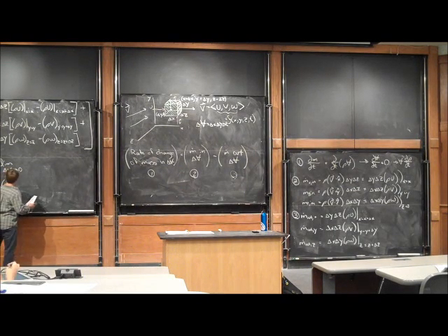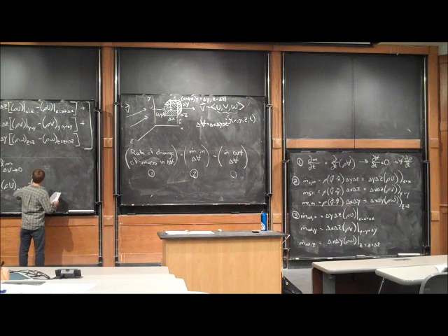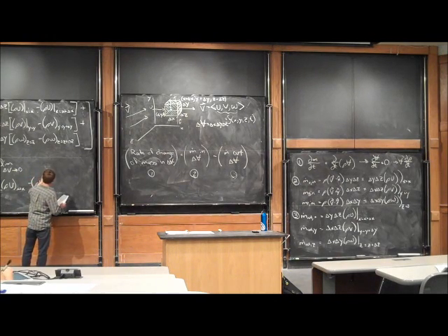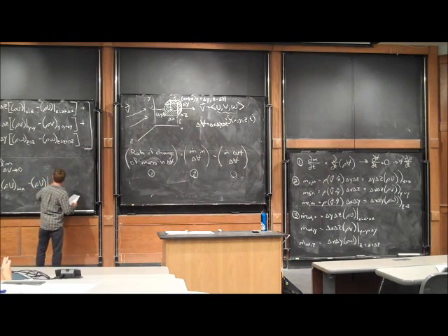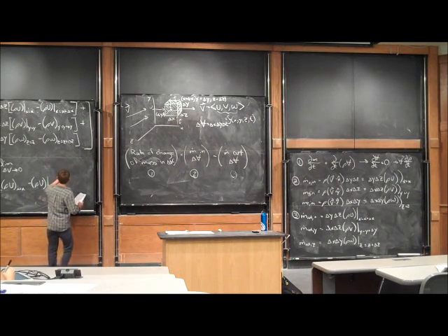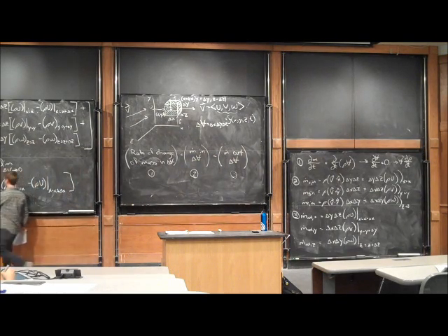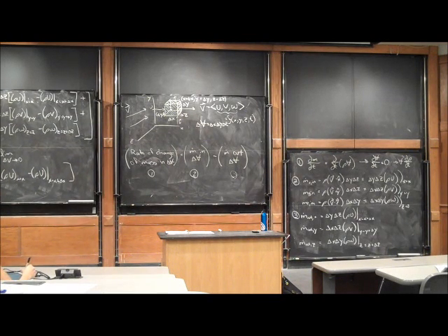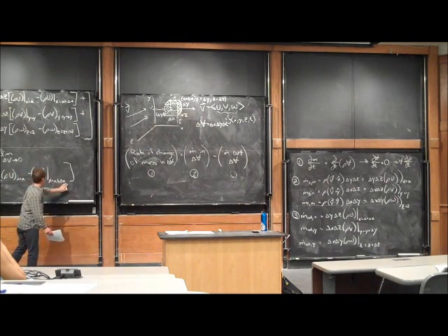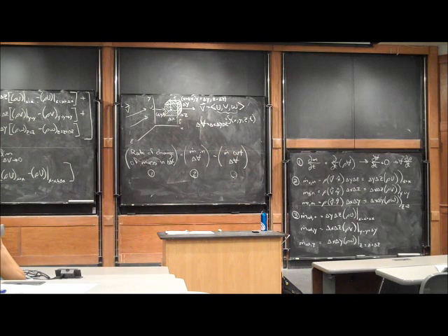So rho u at x is equal to x minus rho u at x is equal to x plus delta x. And I'm taking a limit of this entire thing as delta v goes to 0. But delta v is just delta x, delta y, delta z. I have none of delta y or delta z in my equation, so this is just a limit as delta x goes to 0 of this whole thing.